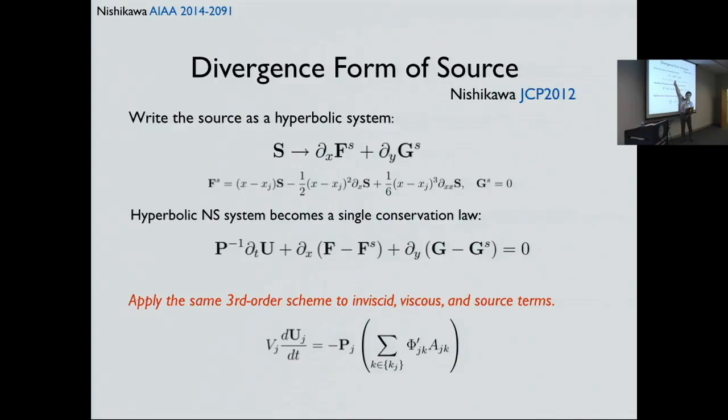And if you ignore this term, you have to have a scheme which identifies this is a shock. Not shock fitting, but you have to at least identify that this is something that I want to draw down. Yeah, okay. But actually, it is possible to formulate this so that I don't need second derivatives. That's what I'm right now working on. Yes, if possible, it's nice to eliminate these second derivatives.